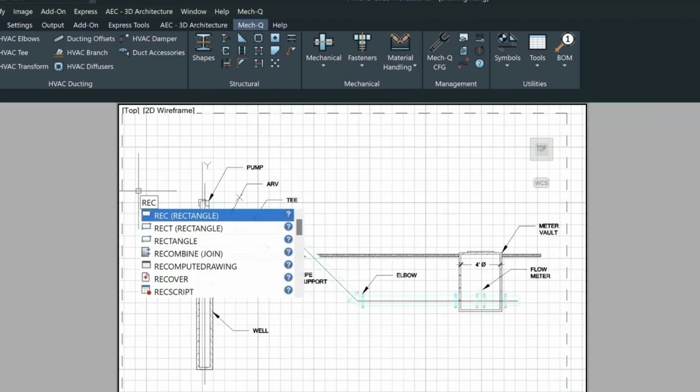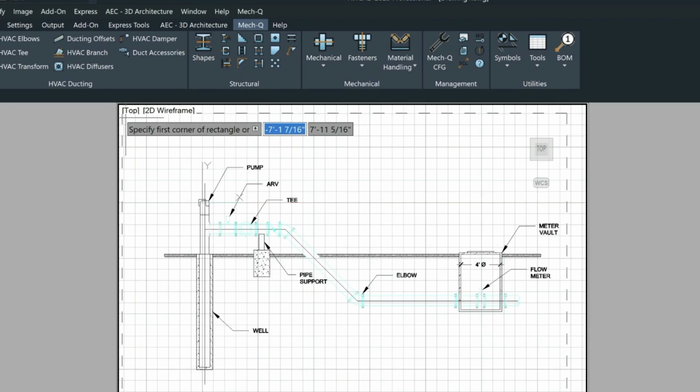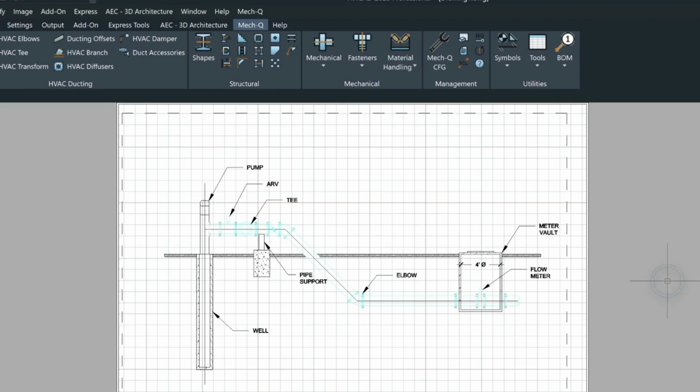Lastly, let's create a border. Notice that this line here is darkened. That means we're still in this model space here, looking down into our drawing. We need to double click out of it over here, and that locks us into what's called paper space. Now, if we type in the REC command and define a rectangle here for our border, and then let's just stretch this down just a little ways.